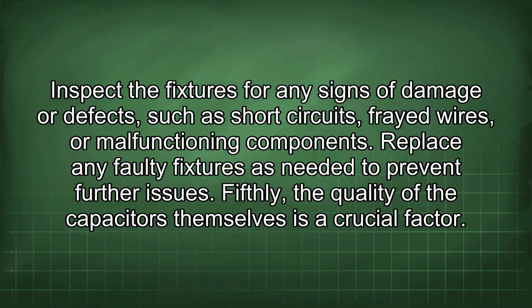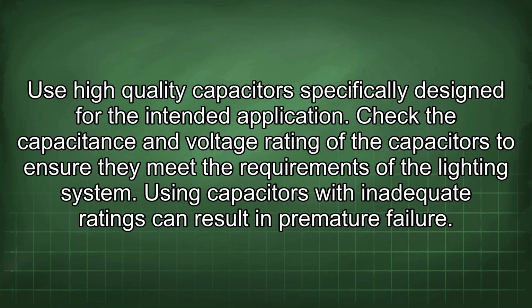Fifthly, the quality of the capacitors themselves is a crucial factor. Use high-quality capacitors specifically designed for the intended application. Check the capacitance and voltage rating of the capacitors to ensure they meet the requirements of the lighting system. Using capacitors with inadequate ratings can result in premature failure.